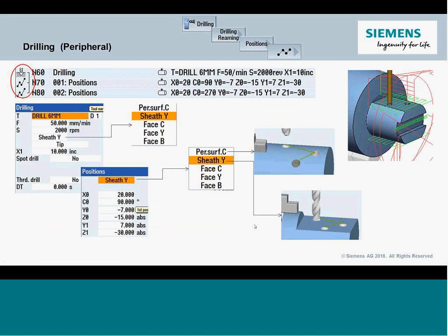I'm going to use the drilling cycles, the live tool drilling cycles that are in the control. We link events just like you would in the lower technology machines. The big thing here is paying attention to the strategy I'm choosing. Is it face, is it peripheral, and making sure I carry the same strategy through from my can cycle to my position locations. If I mix these up, these things won't chain anymore. And the position patterns always have to chain. So make sure that we remember to do that.